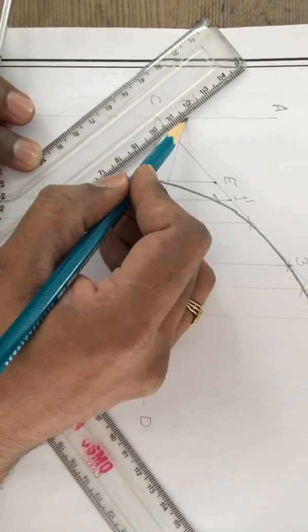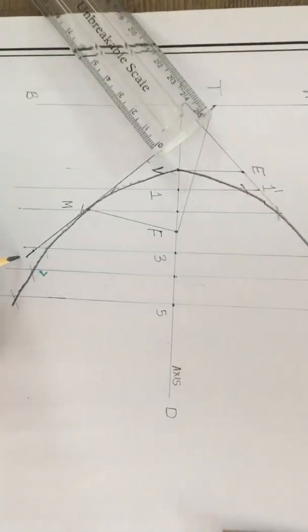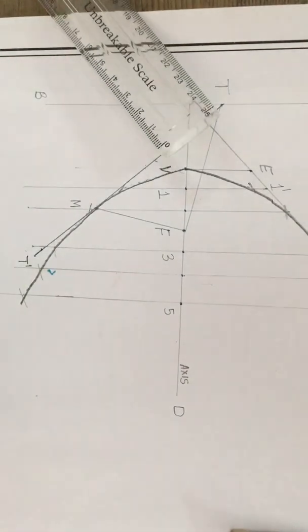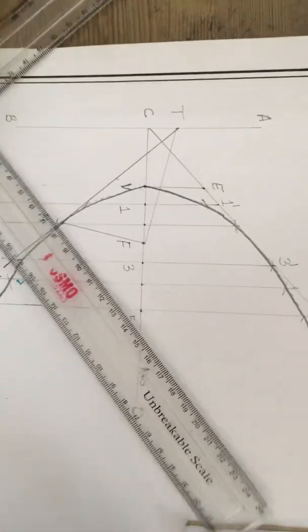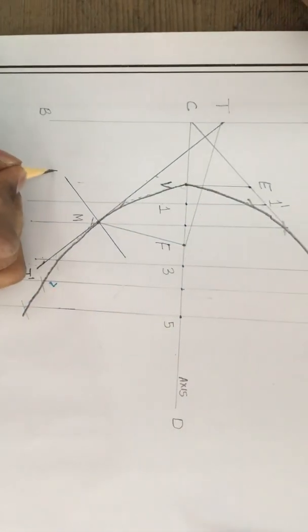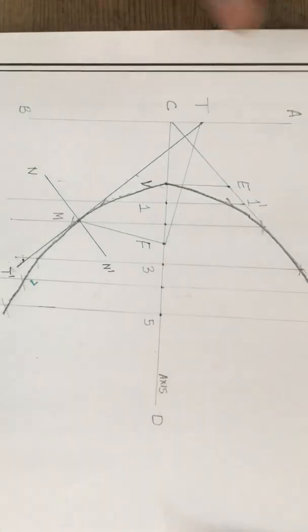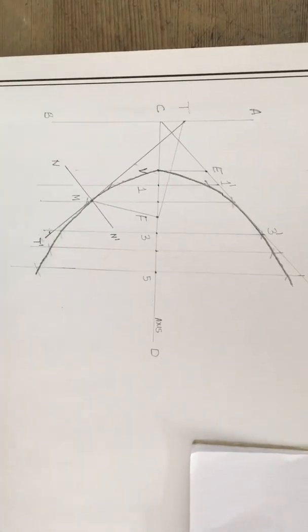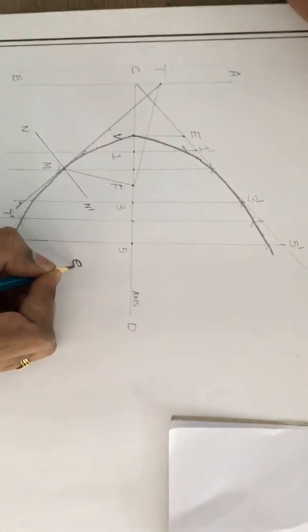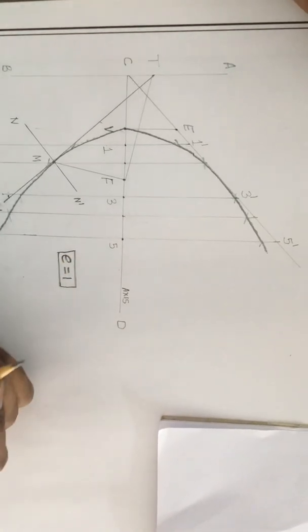So what you are supposed to do? Fix your drafter in such a way that it passes through the point M from T. So this line T dash is nothing but the tangent, dear students, and perpendicular to this is the normal, which is passing through point M. So T dash is the tangent and N dash is the normal. Now do not forget writing e equals 1 here. You are supposed to work out the value e equals 1 after completing the diagram,